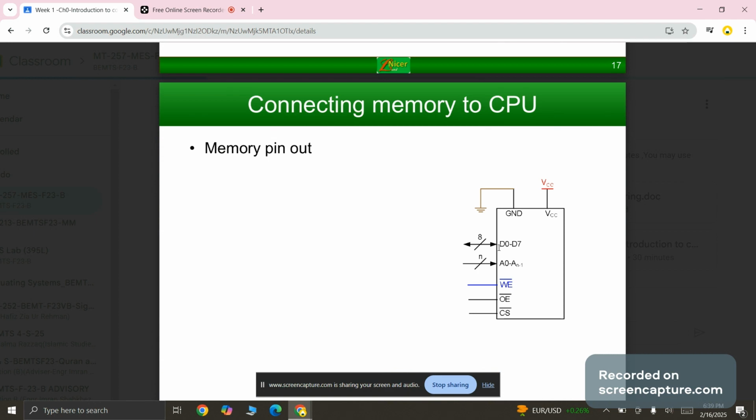Basically, the data output pin transmits the data read from the memory cell when a read operation is initiated. Next one is AO, that is the address output. This pin outputs the memory addresses that are being accessed. The WE is write enable. When this pin is activated, usually set to low logic, it signals the memory chip to perform a write operation.